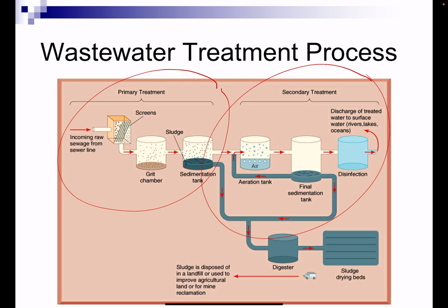Since for the WWTP, the only time that you require a tertiary treatment is if your effluent is due for recycling or to be used in any other process other than just disposing it in any body of water. So for the design that I required of you, all the effluents will just be discharged in the nearest river or any body of water.